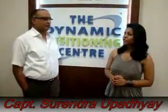Same here. So, firstly, tell me, what is dynamic positioning? Dynamic positioning is a computer-controlled automatic positioning system meant for floating vessels like ships, barges or semi-submersibles. A conventional vessel, which is designed to navigate from point A to point B with a reasonable amount of accuracy, cannot handle the kind of position-keeping accuracy required by operations in the offshore oil and gas industry. Neither can a human operator handle the kind of accuracy required by the oil and gas industry.